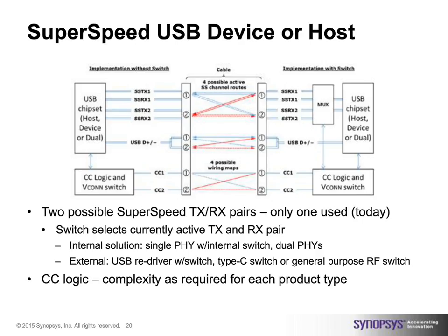For high-speed USB, the reflection is very short compared to the bit time, so it actually works if it's done properly. However, for SuperSpeed, the reflections are always almost as long as the bit time, and the transmitted signal will just be too distorted for the receiver to make any sense of it. So the connection will fail.